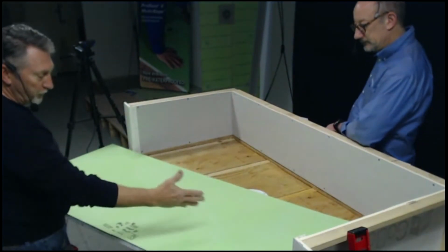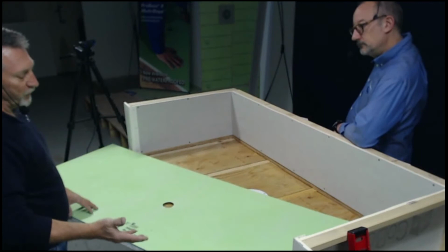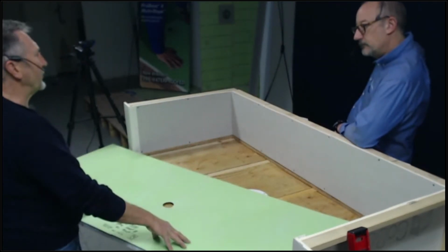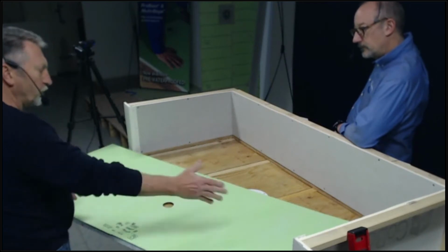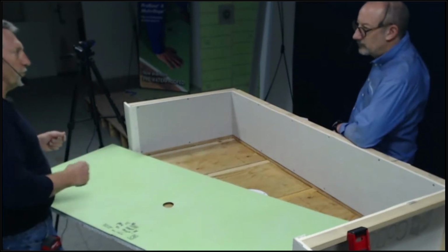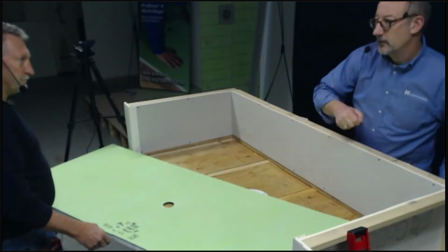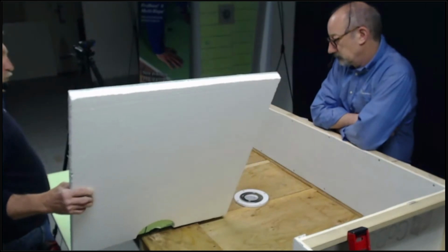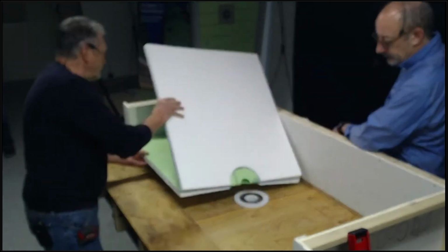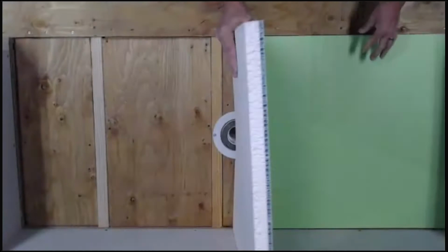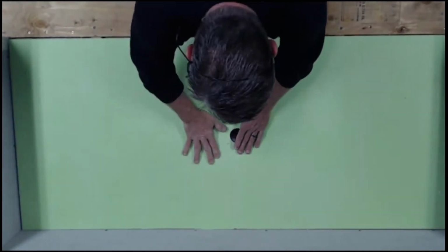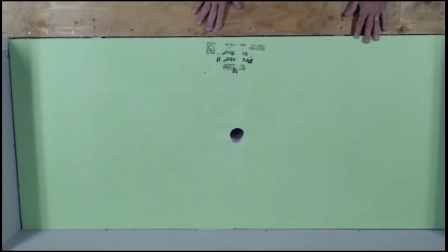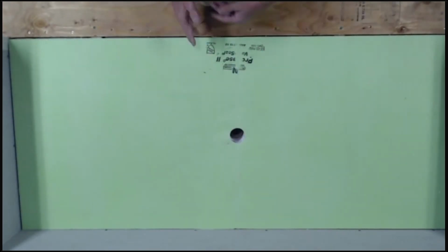Again, there are 2 pieces of ProBase II, the same foam honeycomb composite construction, so it has that same 235 psi compression strength. But we've pre-applied the value seal already to the base. It's incredibly strong. Again, I'll pre-cut and dry fit, making sure my system is going to fit properly before I install it. I feel it fits nice and tight around the drain, so I confirm that I'm ready to install it.